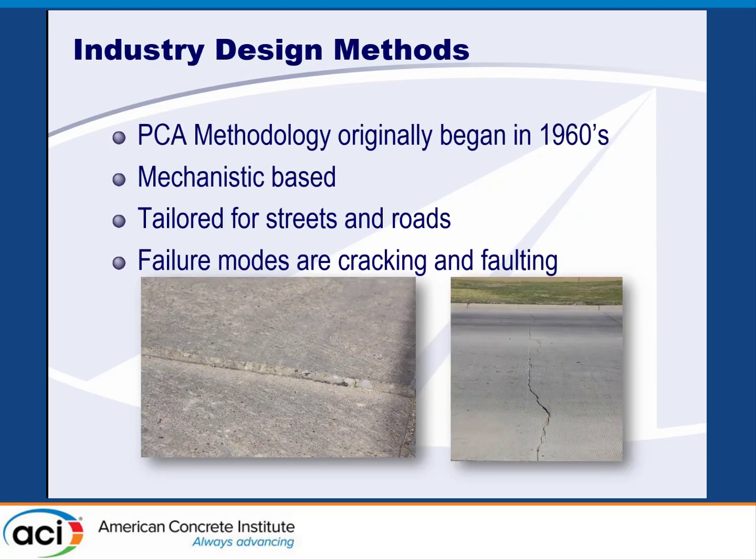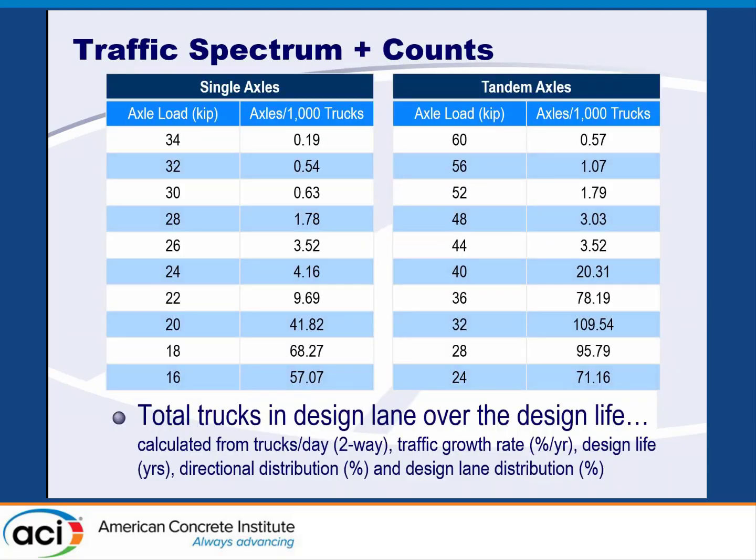And so with Pavement Designer, the big thing that we look to design for is the cracking and faulting. And so we have both erosion and fatigue models within it, but the basis for Pavement Designer is a mechanistic-based design. It's a mechanistic empirical design. And so when we do that, we can evaluate how different types of loadings actually impact the pavement, and we're not just relying on empirical evidence.